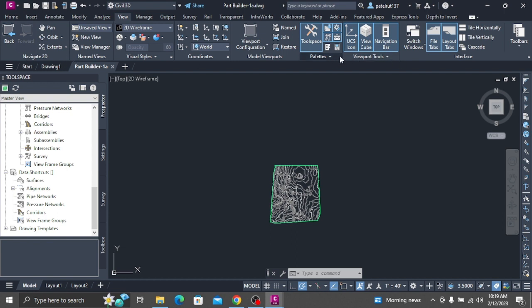Click Save Part Family. Click Yes. Stay in the part builder environment for the next exercise. The part is validated and saved. Expand modeling work planes, right-click Rim Set View. The current view and UCS is set to match the work plane.